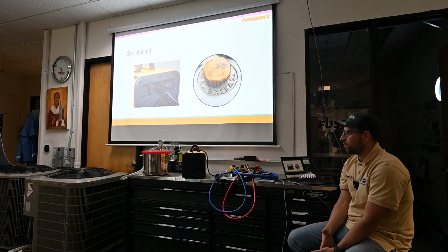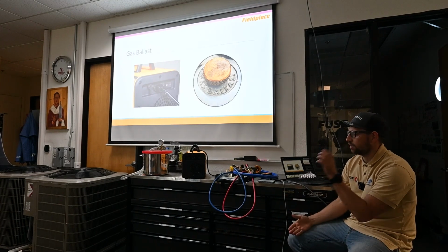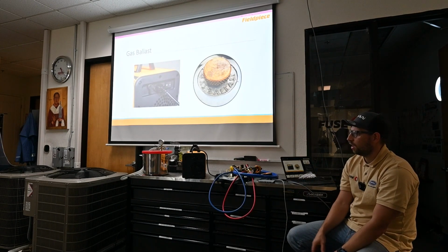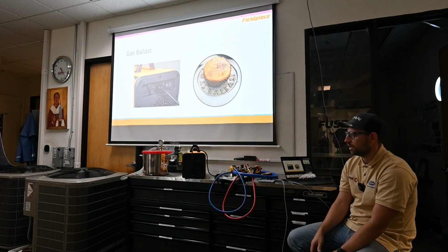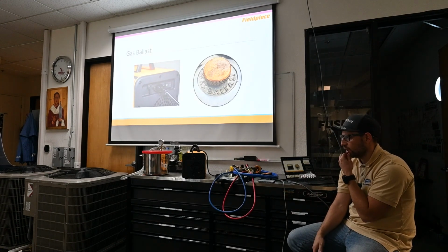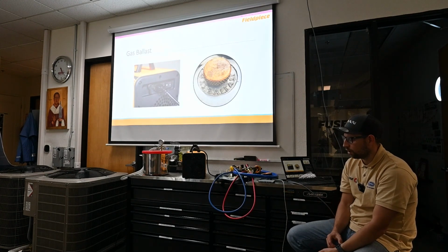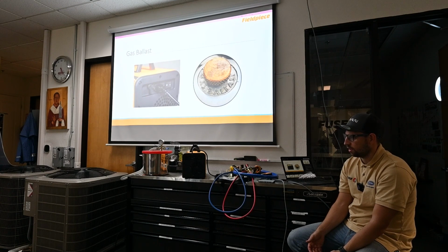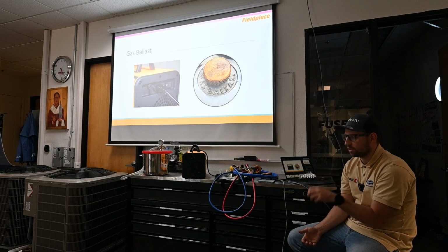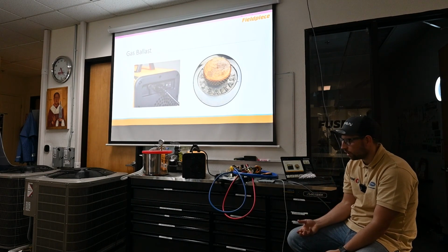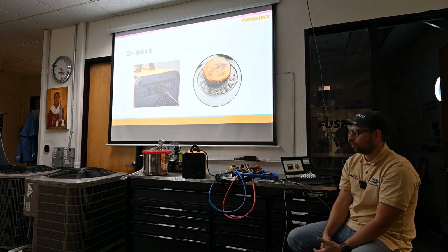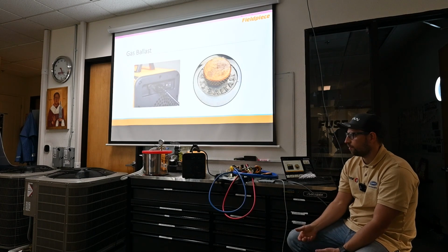When do we need to use the gas ballast? If we come to the field and figure out a refrigerant AC system has a leak, and we decide to just fix the leak and refill refrigerant gas, and we know the leak was probably from the evaporator coil, maybe the system has a water leak. I mean, maybe the system has moisture inside because the leak was from the evaporator coil. We are supposed to use the gas ballast to save oil and decrease vacuum time.